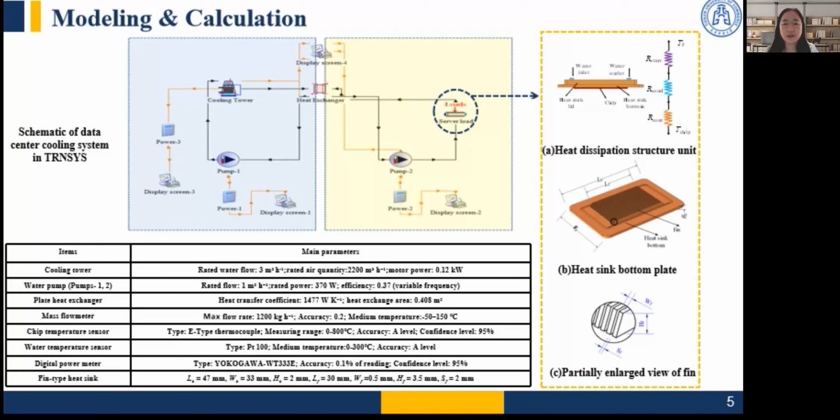In addition, the control module cabinet can display the temperature and mass flow data transmitted by the temperature sensors and mass flow meters in the experimental system. The structure of the water cooling system is shown in the figure, in which the pump uses variable frequency motors to save energy. However, considering the low fan power of the cooling tower for convenience and the cooling system, a cooling tower with a fan without a frequency converter is selected.